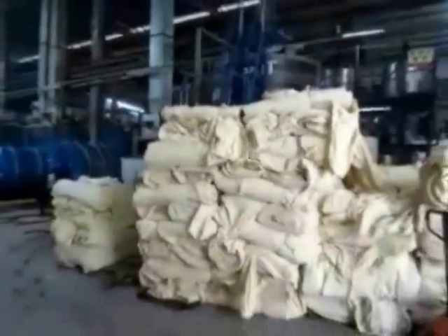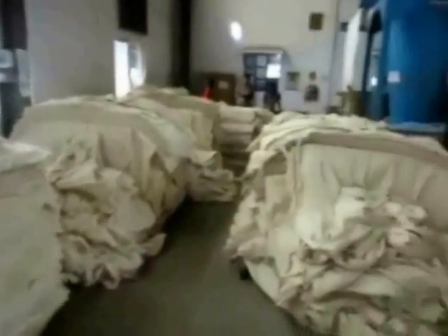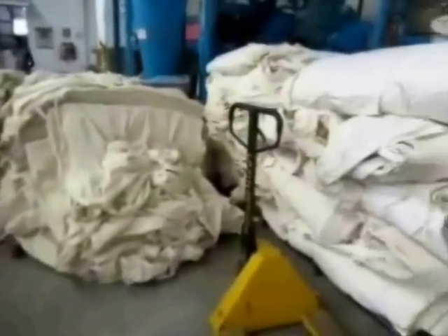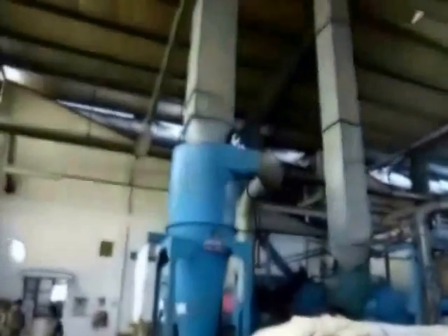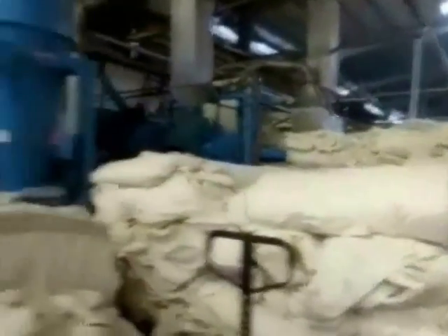In oven dyeing process, singeing comes at first to process the gray fabrics coming from the weaving section. Singeing is the removal of a protruding fiber from the surface of the fabric in order to improve their surface appearance and a sharp surface for printing and dyeing. If not done, this will disturb the appearance of a dyed and printed fabric.